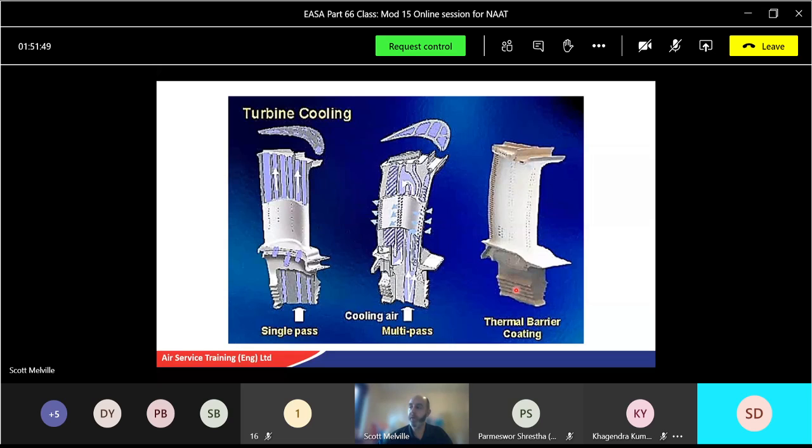And then I've got ones that have a thermal barrier coating. Again, you can see the profile shape of the edge of the blade there, and probably hard to see in the diagram, but that sort of bluish violet colour, that's your cooling air. Now that's great. It makes the blades lighter because you've got the drillings in the blades as well, so we can go faster.